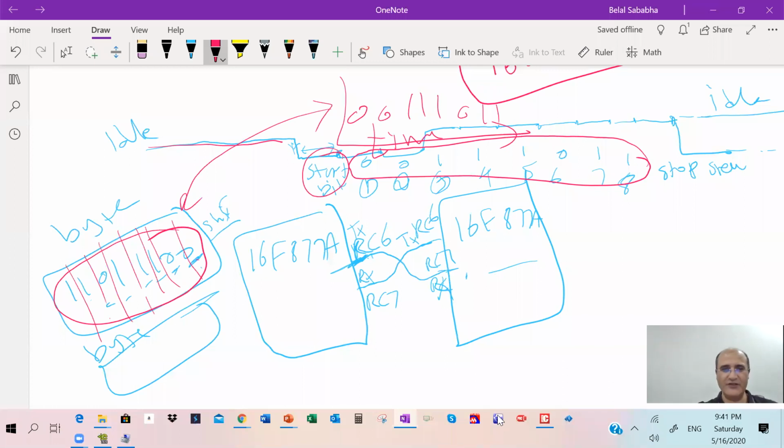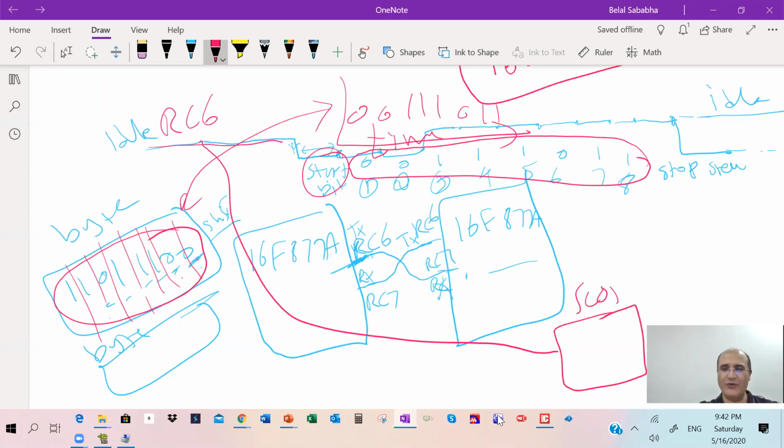Because you take the least significant bit and send it first. So if you take this port C6 and tie it to a scope in the lab when you go back, inshallah, you will see something like this: 0, 0, 1, 1, 1, 1, and so on. Okay.